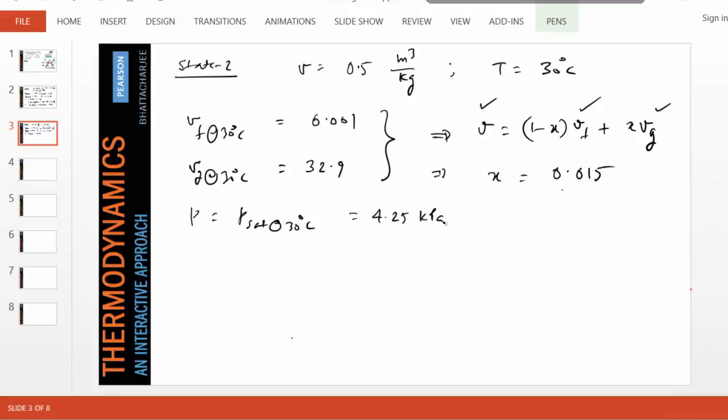So imagine atmospheric pressure is 100 kPa. The tank is almost vacuum. So unless it's made out of really thick steel, the tank is going to collapse. And what we did, we just left the tank overnight, just to cool down. So this is the power of atmospheric pressure.